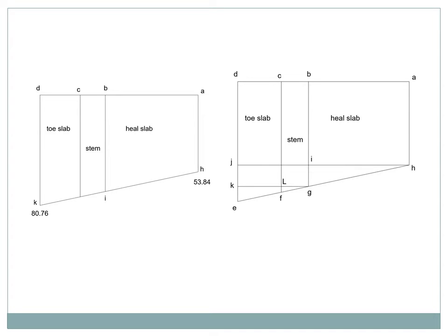Then now we can find out the stem portions, and split into given shapes, triangular shapes or rectangular shapes. The toe slab has two rectangular shapes and a triangular, then stem also two rectangular and a triangular, then heel slab also one triangular portion and one rectangular portion.